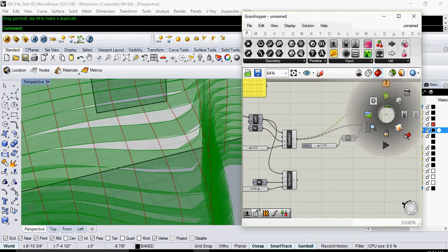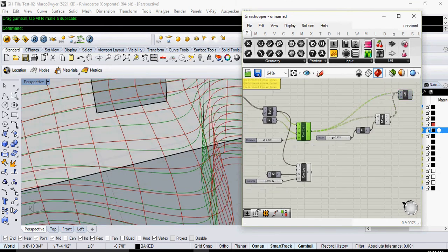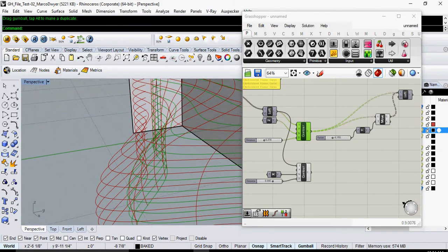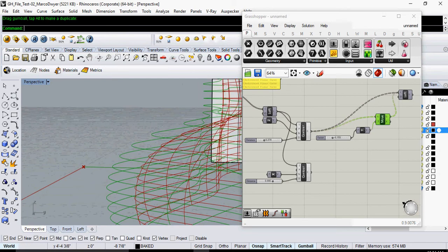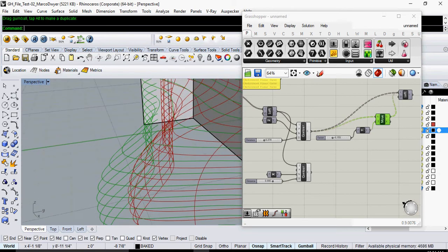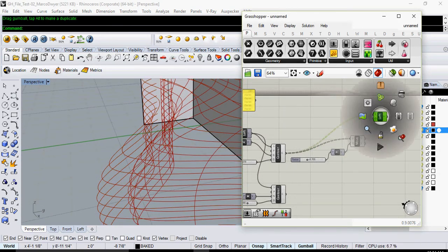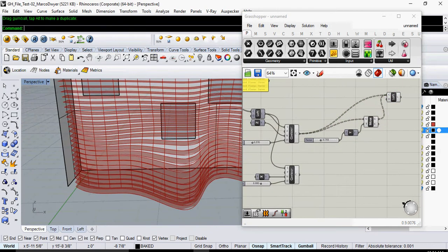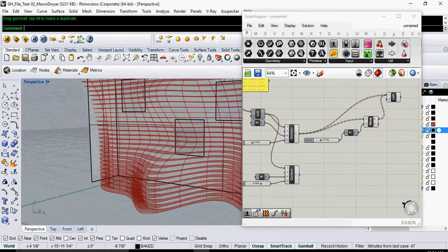And then just hide it for a second. So you have this contour, which is the original contour we had, and the move geometry, which is the surface, which is the curve moving forward in one direction. We just lofted it, so that way it creates a surface. Preview it. Alright, we're going to do the same exact thing, but for this one.